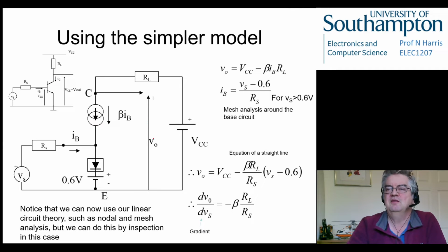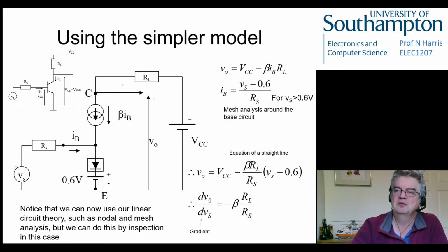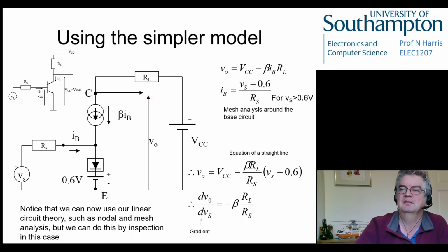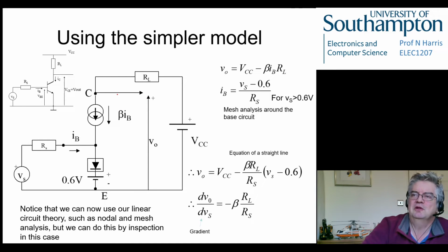We're interested in the output voltage, and the output voltage is defined as the voltage across this transistor. So we want to take the voltage at this point here, and that's this point on the circuit. So we are interested in this voltage in this mesh or loop. With a bit of common sense and a bit of looking at this, we can say this voltage here could be the sum of the voltages across here, but we've got a current source here, and we're never sure what the voltage actually is across a current source.